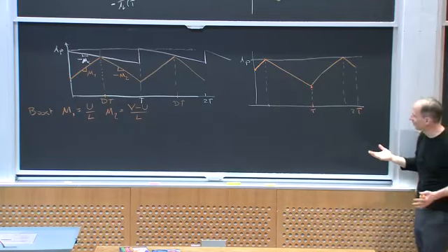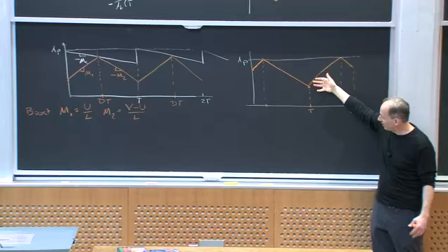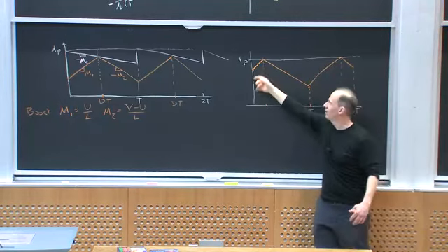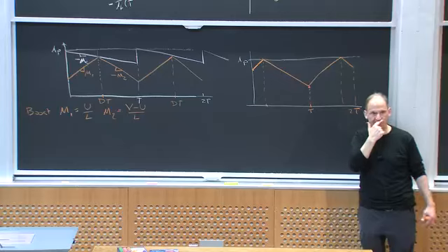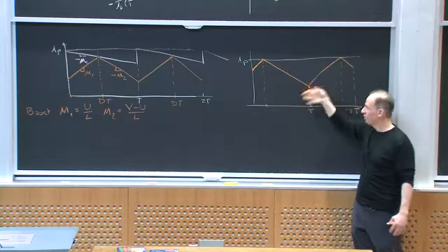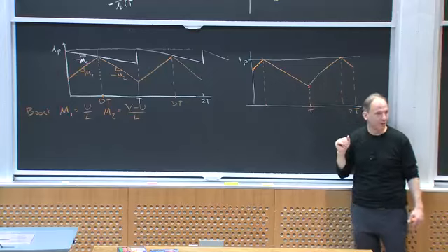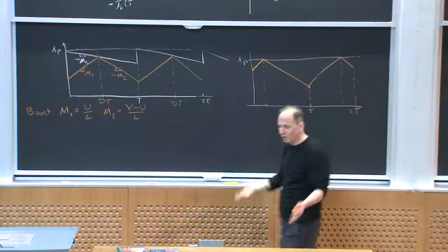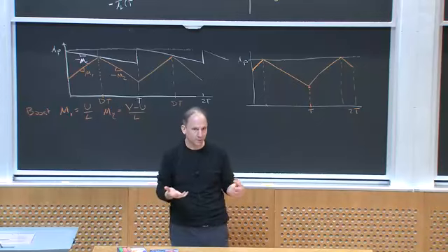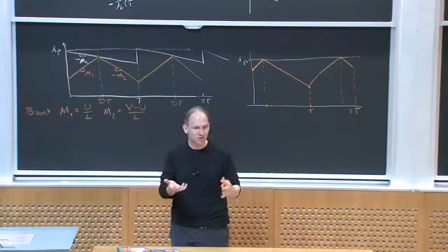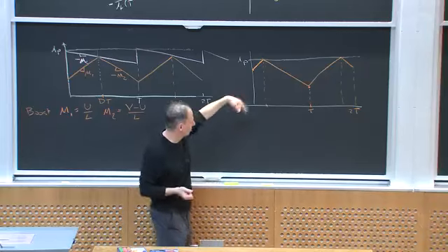One perspective is my ripple in this case is a heck of a lot bigger than if I were at some fixed intermediate duty ratio. So I get much bigger ripple. The control is jittery because it's bouncing around depending upon the operating condition. I have lower frequency content in my output ripple. It's bigger ripple and it's lower frequencies. That can make a mess of things, so people don't like this behavior.